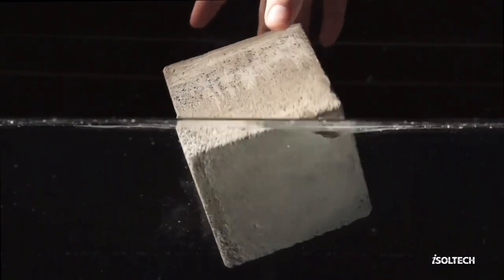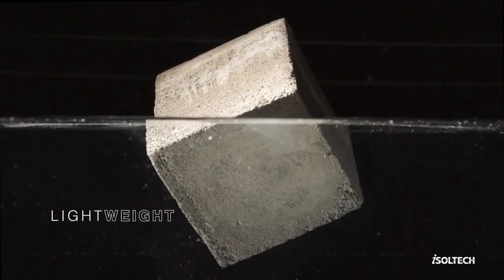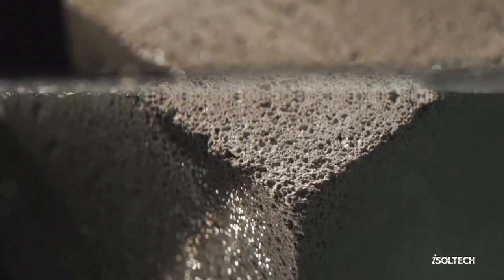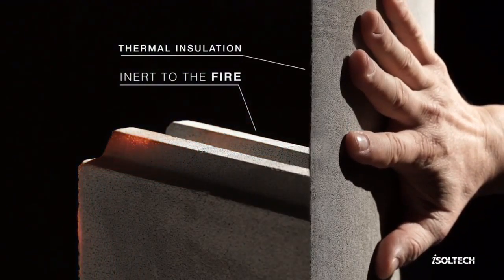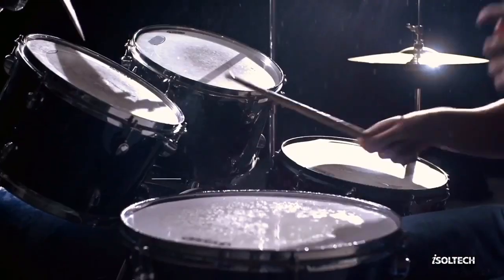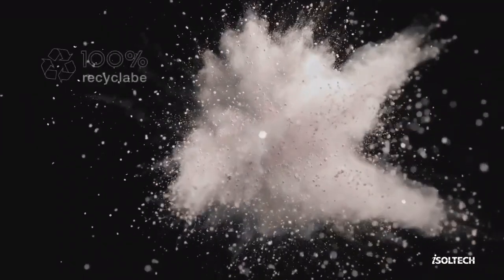The low density of cellular concrete makes it suitable for precast floor and roofing units, which are easy to handle and transport from the factory to the site. Fire resistance: lightweight concrete has excellent fire resistant properties. Its low thermal conductivity makes it suitable for protecting another structure from the effect of fire. Sound insulation: sound insulation in cellular concrete is normally not as good as in dense concrete.